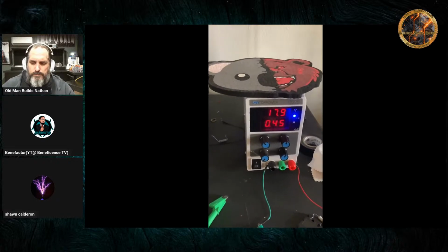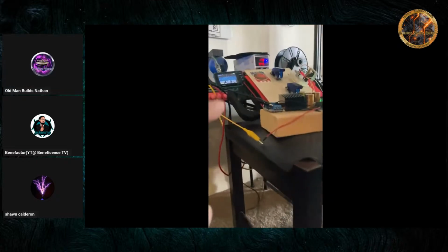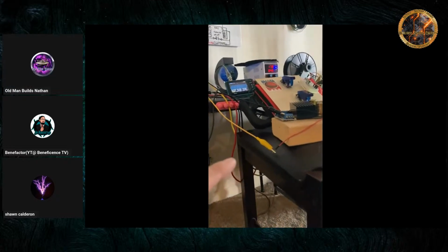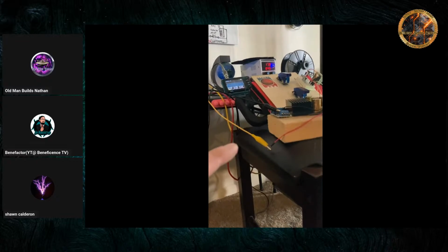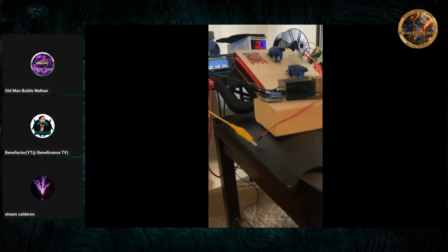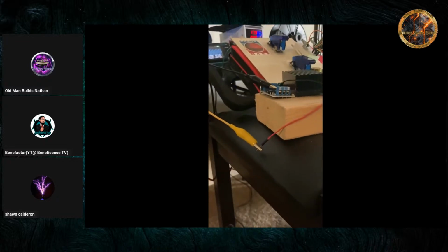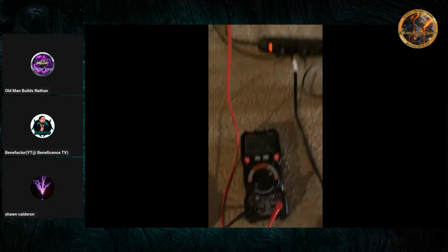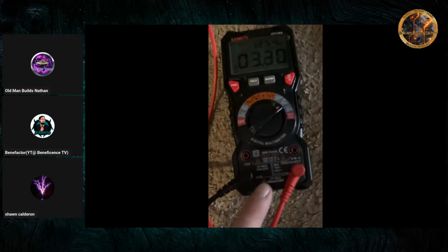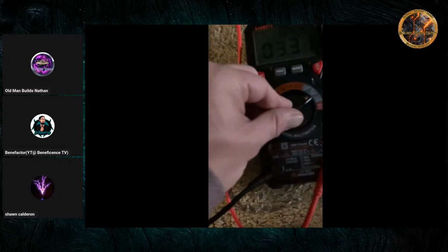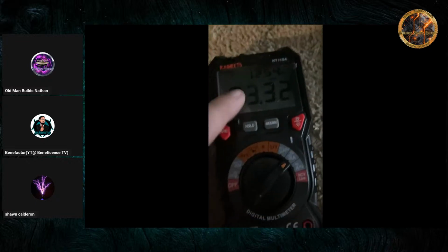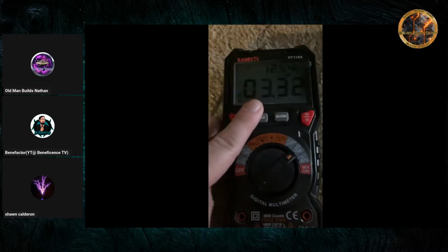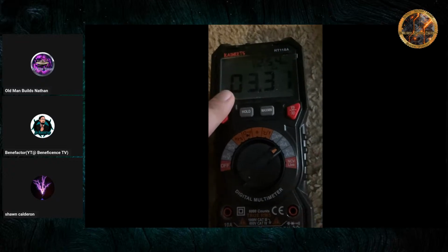Might be a more accurate current reading. We have 0.45 amps going into the stereo amp. I just measured it. I'll measure it again in a second, but we have 3.05 milliamps coming out. So a significant loss in the amperage. I'm not sure if that makes sense, but the current is being read correctly because the settings are correct now. Before I couldn't get a reading except on DC, and I was like, well, this might not be accurate if it's on DC and not AC.